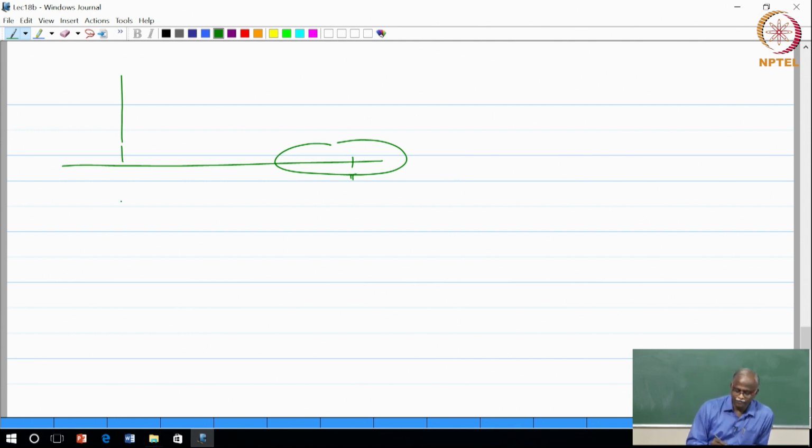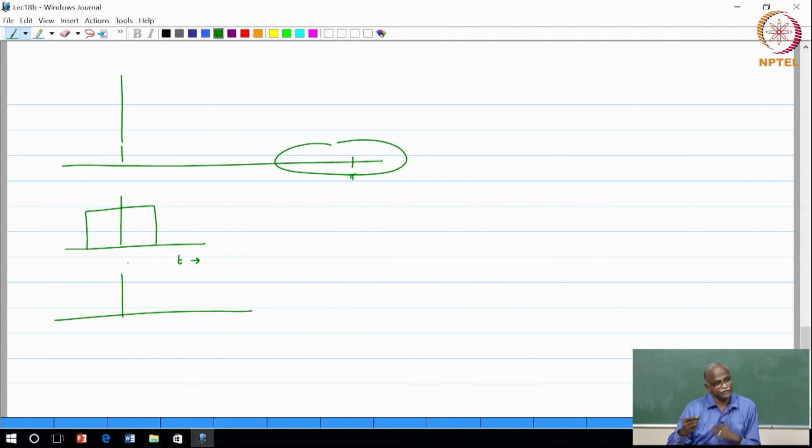So, for example, if I were to have a brick wall in the time domain, you know that this is infinite in frequency in continuous time. So basically what you will get is something that will keep going. Was there a sharp transition in the time domain? Yes, because you took a rectangular window. So, what did you do? You took a segment.